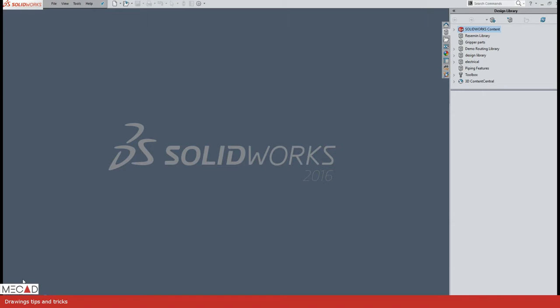I'm going to be covering detached drawings in this session on its own. I believe this is a very powerful functionality in SOLIDWORKS that not many people use or even know exists. Detached drawings allows me to take a normal SOLIDWORKS drawing, keeping it in the same file format, and breaking the link between the assembly and the drawing temporarily. Let me show you how this works.